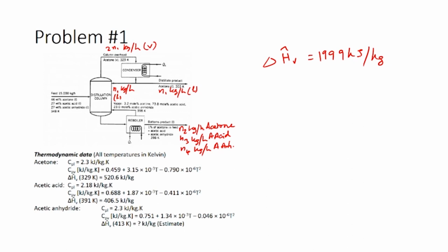So, to calculate the mass of steam required, we would have to calculate QR dot divided by delta H cap V, which would be roughly equal to 4070 kilograms of steam per hour. So, by condensing 4070 kilograms of steam which is saturated at 10 bar per hour, we will be able to generate the amount of heat required by the reboiler. So, this gives us a way to calculate the energy balances, and we have tried to use multiple concepts which we have learnt over the last few lectures to apply here.